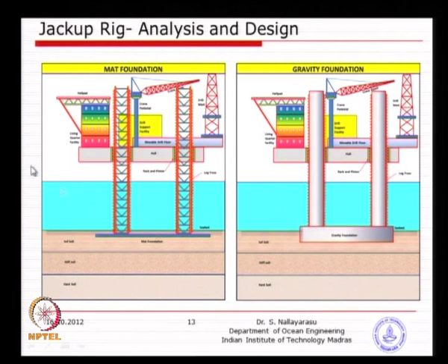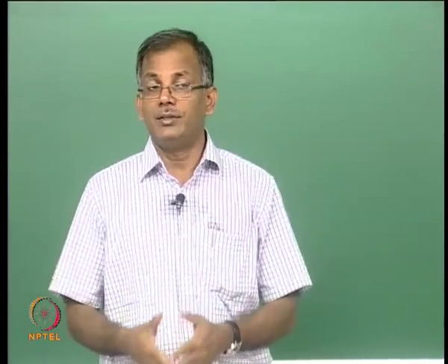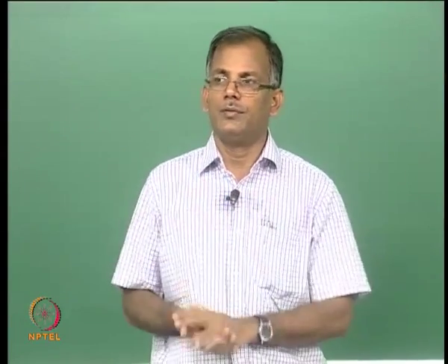You will see that this type of structure is very rarely used, because transportation becomes very difficult unless it is a one time structure located for one particular location. For example, a fixed offshore platform built of concrete is not going to be moved every few months. So, you construct it and leave it there, whereas if you make it very heavy, deballasting it next time to transport from one location to another becomes a substantial offshore exercise, which we really do not want.